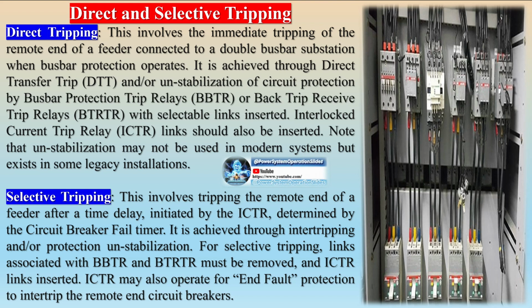A fault is indicated if the check zone currents do not sum to zero, regardless of the disconnect switch's status. If the normal differential operating current is non-zero and the check zone operating current is zero, a faulty disconnect status contact is likely the cause. Check zone supervision of the normal differential element significantly reduces the risk of a false trip. Current direction: there are additional options for a second trip criterion to supervise the differential element.